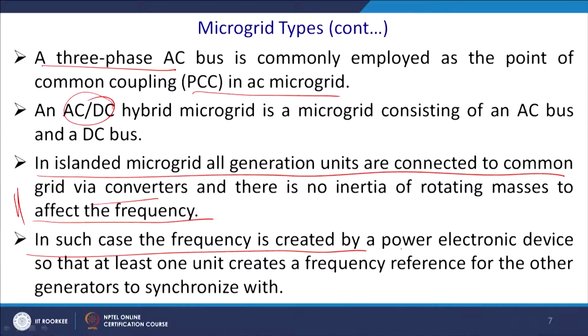They have an entity called Sunny Boy, which forms the grid, and all other inverters follow it. So at least one unit creates the frequency reference for the other generators to synchronize to.